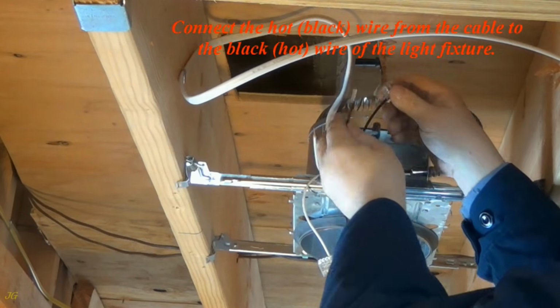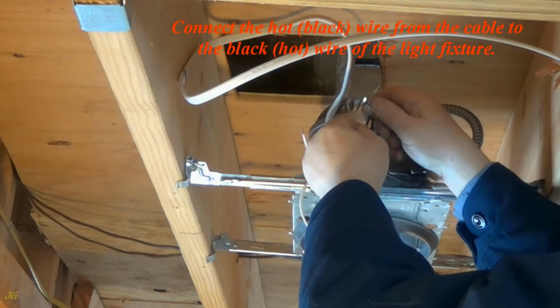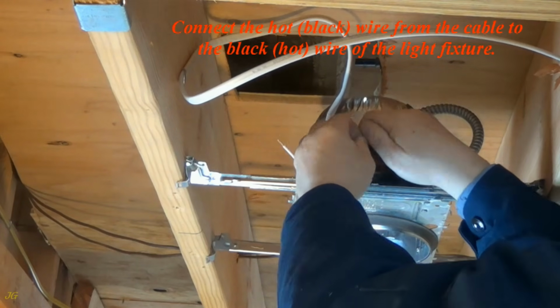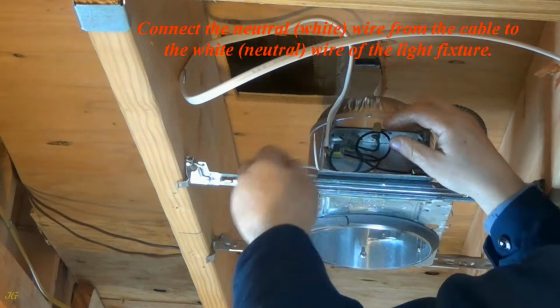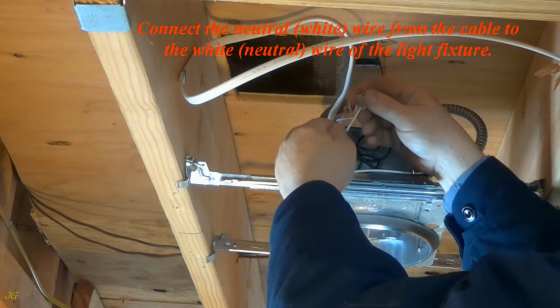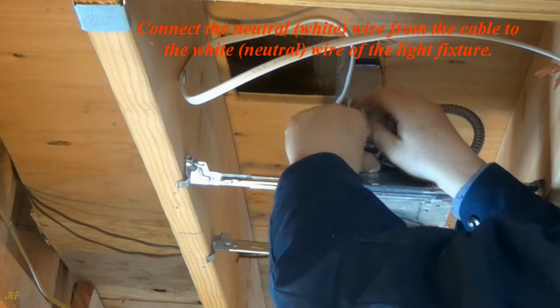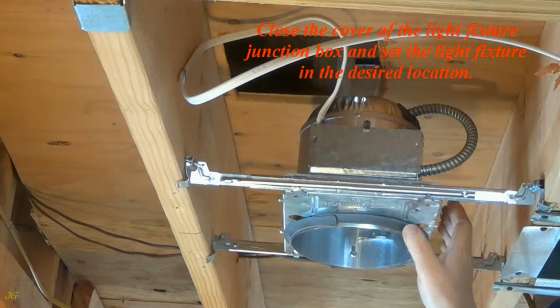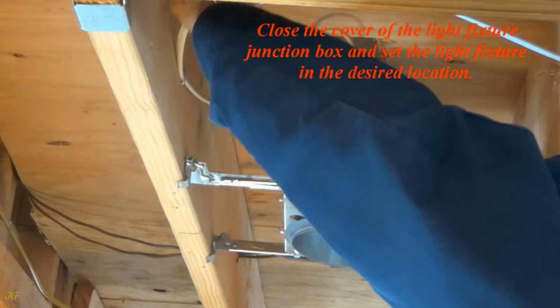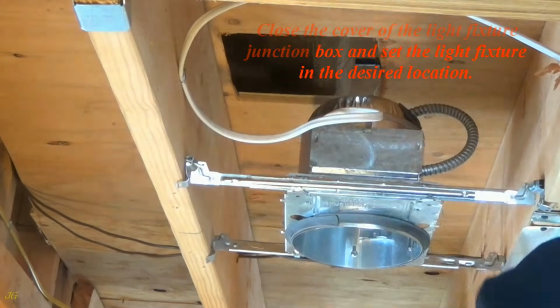Connect the hot, black, wire from the cable to the black, hot wire of the light fixture. Connect the neutral, white, wire from the cable to the white, neutral, wire of the light fixture. Close the cover of the light fixture junction box and set the light fixture in the desired location.